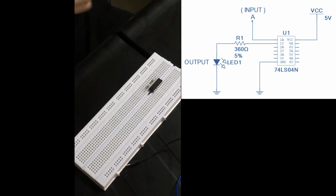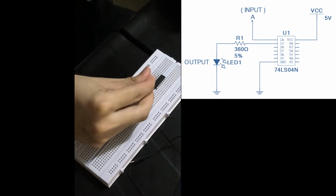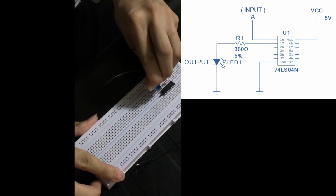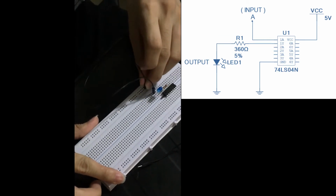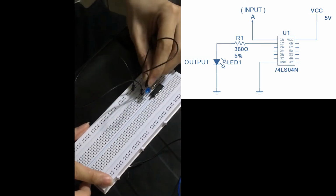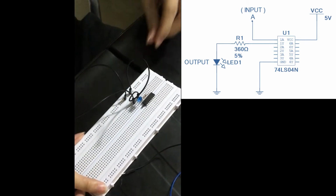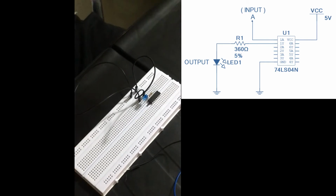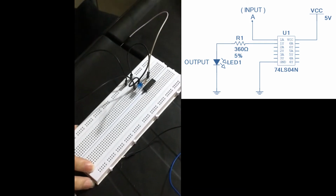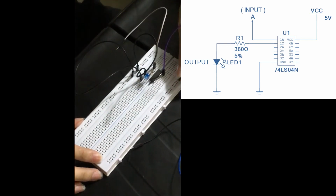Following the diagram, we will be using the 360 ohm resistor connected to the second pin of the IC, followed by the LED connected in series with the resistor and the negative to the ground. The 7th pin as well is connected to the ground. The VCC is connected to the positive of the 5 volts power supply. On the first pin, we will be connecting the input.